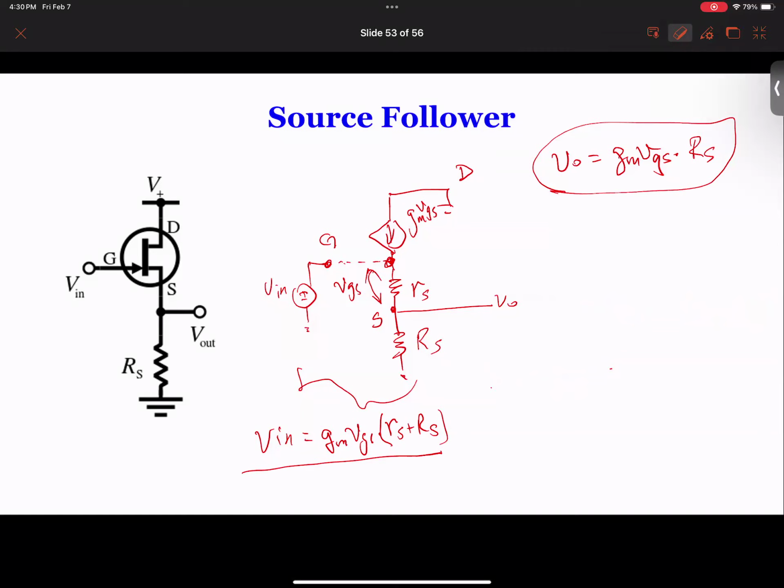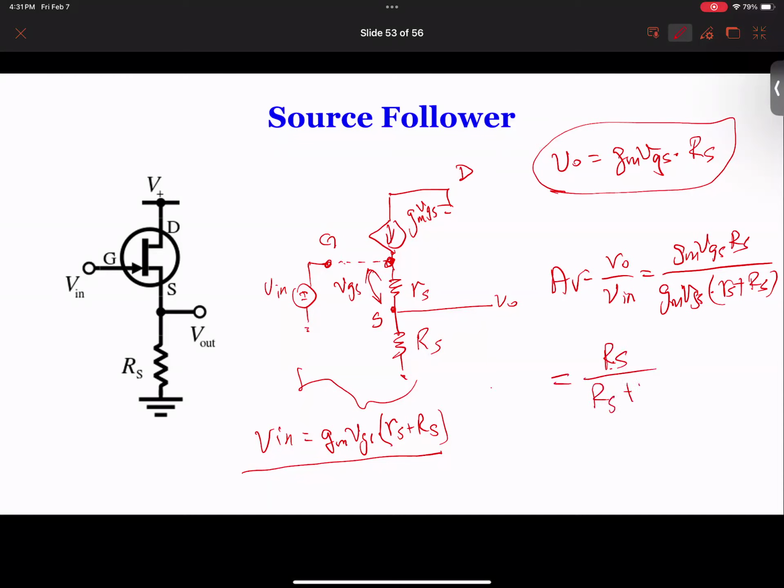So now I can write Av equal to Vo over Vin. So this is gm times Vgs times RS divided by gm times Vgs times RS plus rs. Actually, I didn't have to solve for gm times Vgs because these two are going to cancel. So therefore, I got Av equal to basically RS over RS plus lowercase rs.